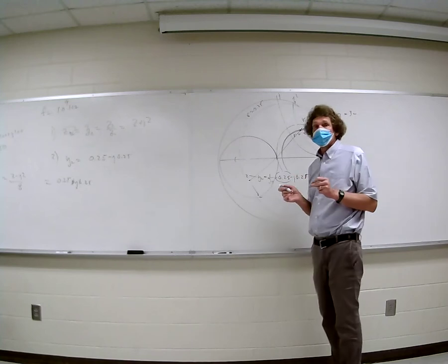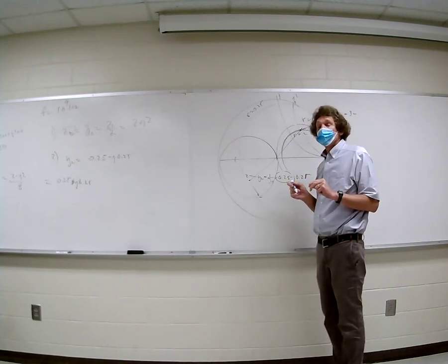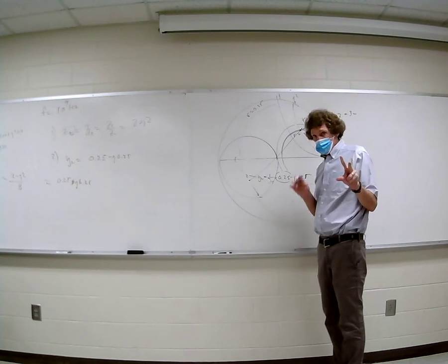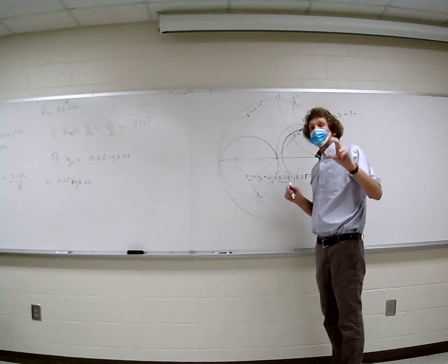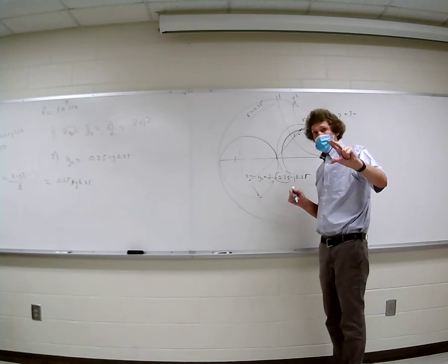Here's a tip. Anytime you're given that option, if it's an admittance component, a parallel component, always use a capacitor. In other words, plus j something. The reason is the capacitor blocks DC. A capacitor will block any kind of short to ground that could happen.